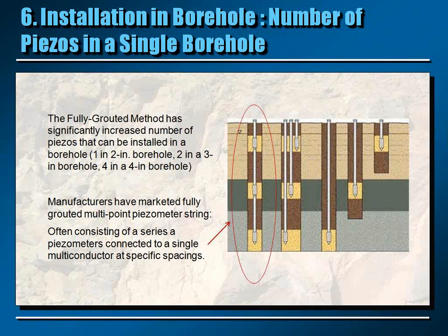As I mentioned, one advantage of this method is that now it's possible to install more piezometers in the same borehole. You can install one in a 2-inch borehole, 2 in a 3-inch borehole, 4 in a 4-inch borehole. And even more than that, if you use the new type of piezometers that were developed by manufacturers recently, which are the multi-level piezometer string.